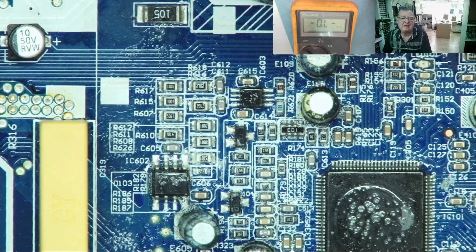The important thing here is do not be concerned about resistors in circuit that read lower than they should do, okay? When I say lower than they should, I do not mean if they read 0 like a short, because it's not reasonable really for a resistor to have a short across it, otherwise why have the resistor?